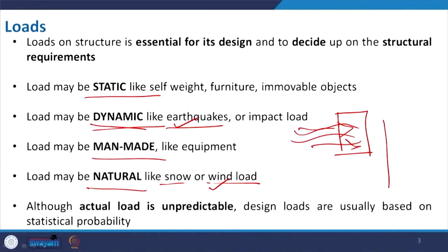So when we design the structure of a building, we should take into account all possible loads that may affect the building design, that may deform the building. In order to make your building resistant to all applied loads, starting from the self load to the additional furniture load, or maybe some natural load, wind, rain, or maybe earthquake, flood, we should calculate that. In structural calculation there are different handbooks from which different input parameters will be taken into consideration.